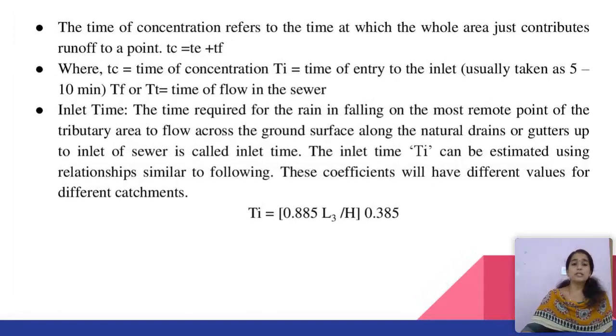The time of concentration refers to the time at which the whole area contributes runoff to a point. That is, TC is equal to TE plus TF. This can be written as TI plus TF, where TC is the time of concentration and TI is the time of entry to the inlet, usually taken as 5 to 10 minutes. And TF or TT is the time of flow in the sewer.